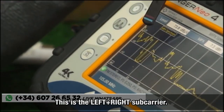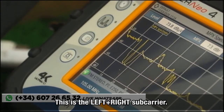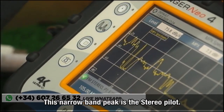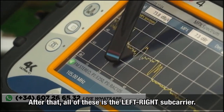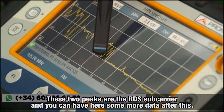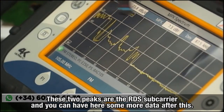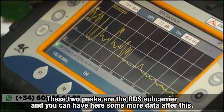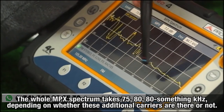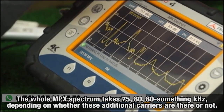For example, here on the left, the first component, the first subcarrier, would be the left plus right subcarrier. Then this narrow band peak is the stereo pilot. After that, all of this is the left minus right subcarrier. These two peaks here together are the RDS subcarrier, and you can have even more data after this, another carrier. The whole thing together usually goes up to 75, 80-something kilohertz, depending on whether these additional subcarriers are there or not.